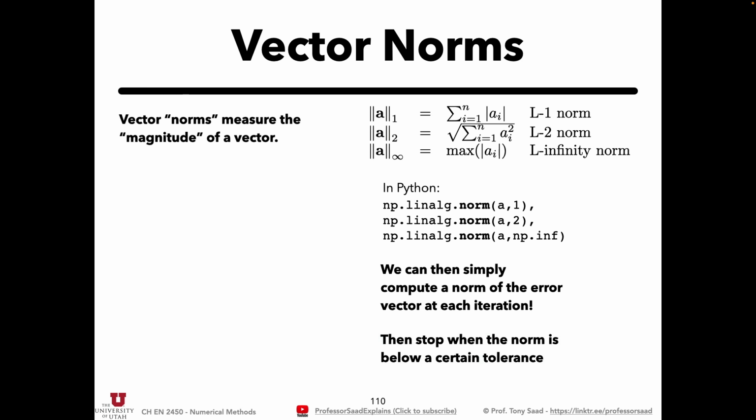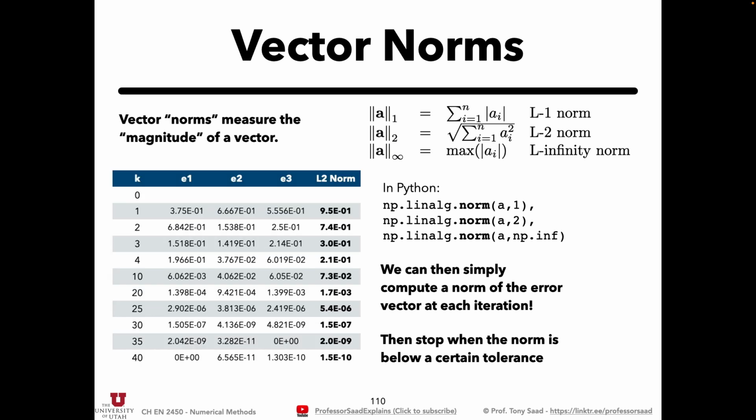So you're no longer measuring the error for a single value anymore. You're measuring the error for a collection of values. Each value has its own error. You need to aggregate all those errors together. You can take the average, you can take their sum, you can take the square root of the sum of the squares. They're all reasonable. They will all be close to each other within a few iterations, but you have to choose one of those as you're designing your solver.